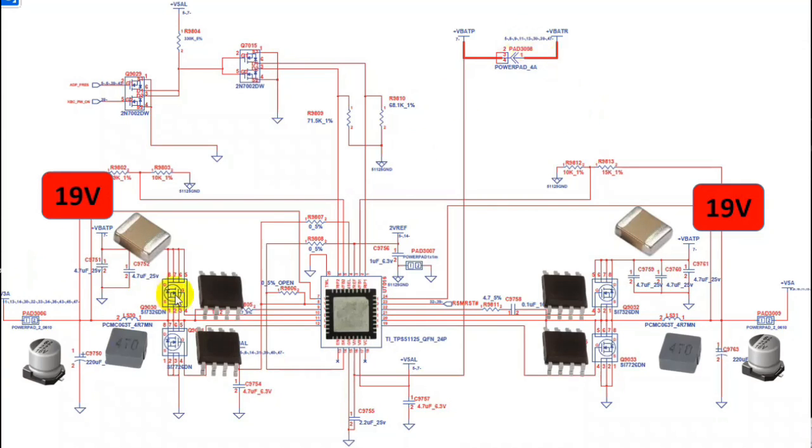So as you can see here, this is basically the 3 volt, 5 volt circuit. Here we have plus 3 volt always, and here we have plus 5 volt always. Basically this circuit is responsible for generating these voltages. This 3 volt, 5 volt circuit is divided into 2 channels, as you can see. Here we have the first channel, and over here we have the second channel. All channels are the same, as you can see, the same components here as here.